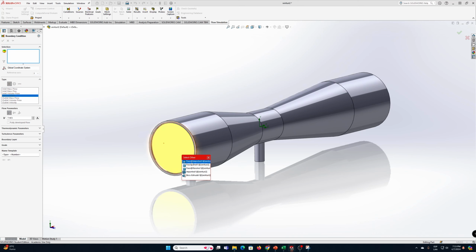And you have to use the one that represents the imported name. You can also verify it, because it's like a cube with a circle in the middle. So use that option, the one that says imported. Now here, we already selected the value of the flow opening and the value of the velocity. If you want to put some temperature there, you can also put it here.